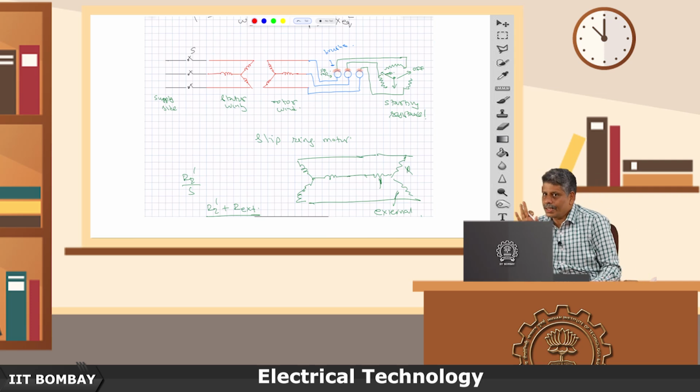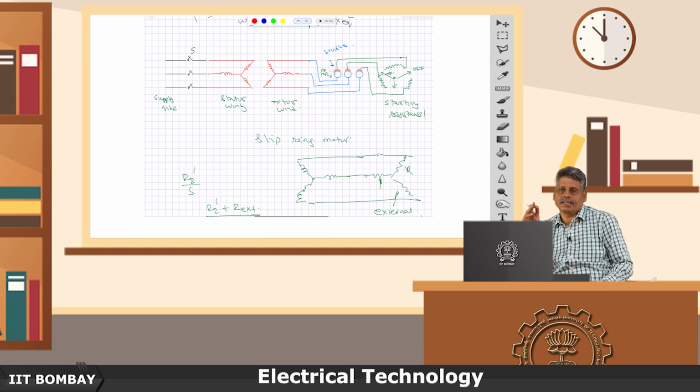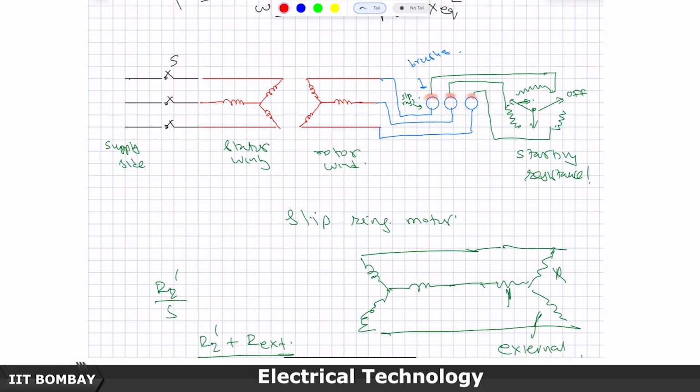You should not run an induction machine with external resistance included in it at its full load condition, because then I square (R2 dash plus X Thevenin's dash), which is the loss happening in the rotor winding, is going to be significantly more. If the heat generated is significantly more, then the machine cannot be run for more than 2 to 3, 4 hours before it will start getting excessively heated.